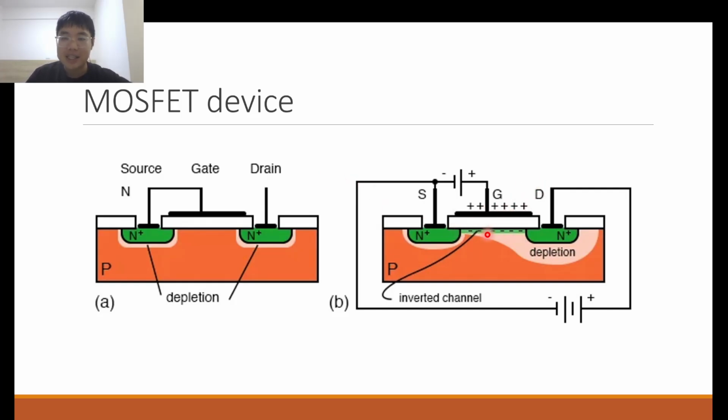So let's say it is indeed greater than the threshold voltage. We have a channel consisting of electrons. We call this an N-type channel, because it consists of negative charge carriers, electrons. So an N-type channel forms, and we have an N connected to an N by an N-type bridge. This turns on the transistor, and current can flow from the source to the drain.